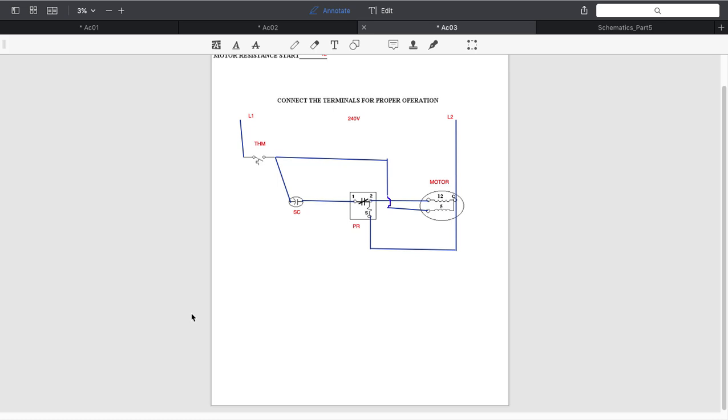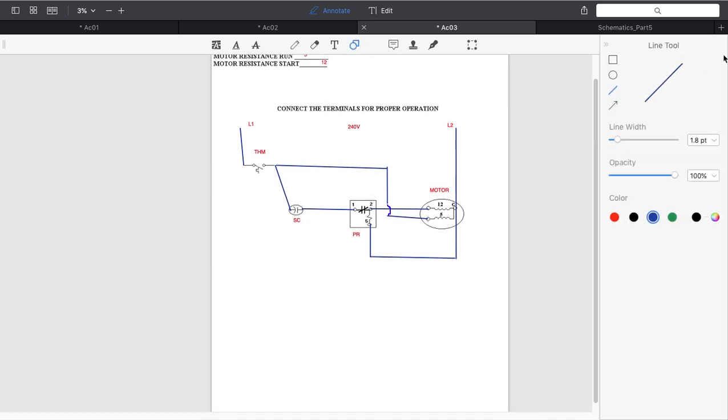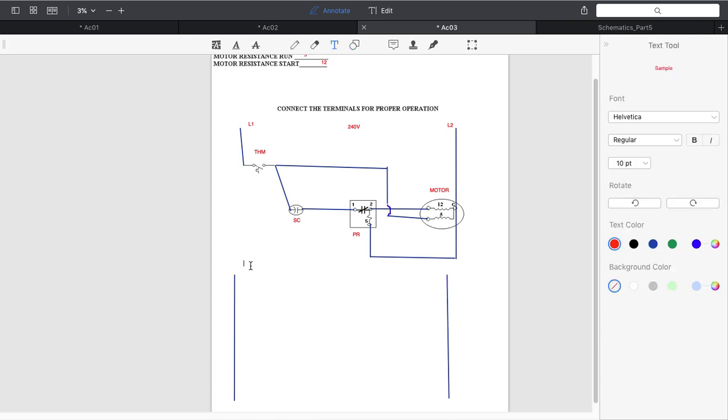Now, since we know a pictorial, let's go ahead and draw a ladder real quick. And again, I do use some shapes and some symbols that I have on a symbol sheet. But let's start by drawing our ladder. The ladder has supports, or the supply voltage lines. We always want to start with that. Never forget about that. L1, L2. Let's go ahead and say what voltage we're using. Again, don't forget about it.